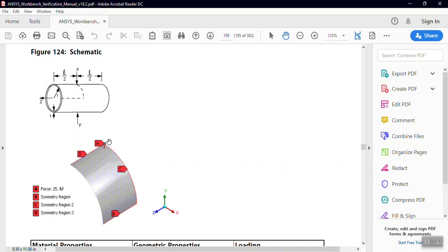Suppose there is a rotation about the x or y axis, again there will be a movement out of the xy plane. Since the nodes on the xy plane should not move out of the plane, rotation about x and rotation about y are also 0. So for xy plane symmetry, Rx, Ry and uz are 0. Similarly, for the xz plane, Rx, Rz and Uy will be 0.